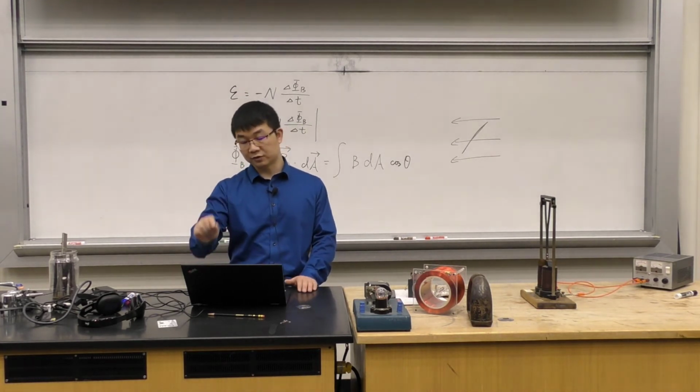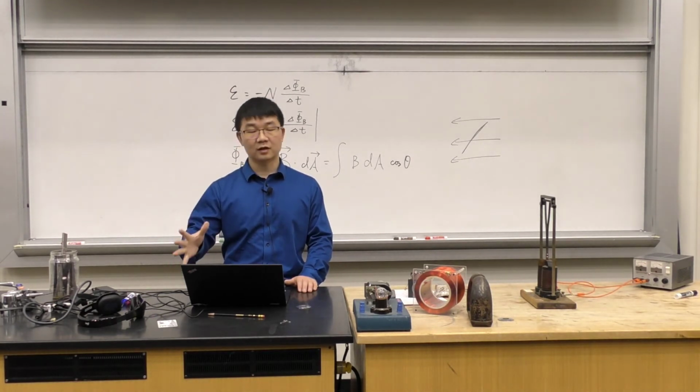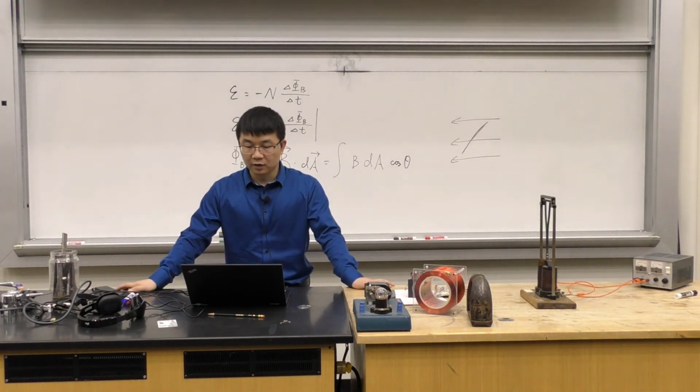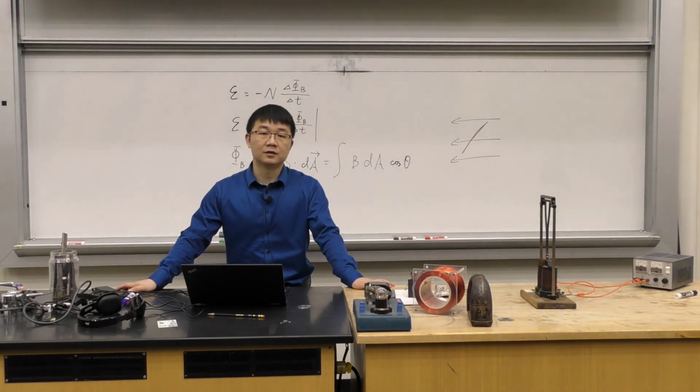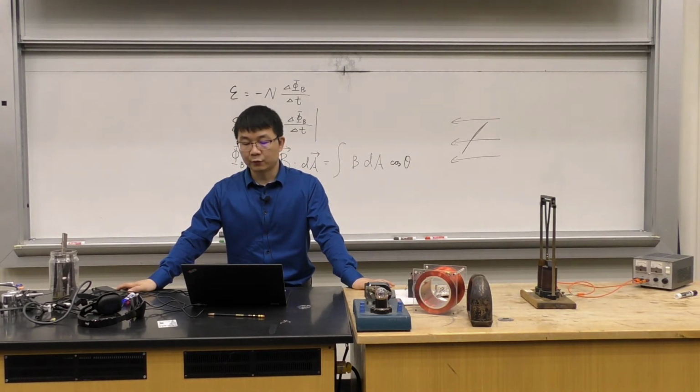Remember, the receiver coil is not connected to a source, so there's no current there. Only because the metal inside the box now has induced currents, a lot of loop currents, these loop currents have their own magnetic field B prime, and this B prime goes through the receiver coil on the right, so they will cause another induced current in this receiver coil.